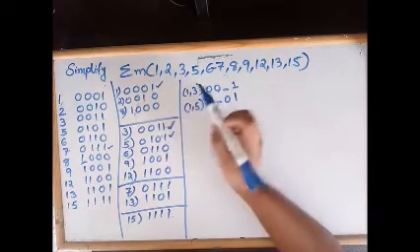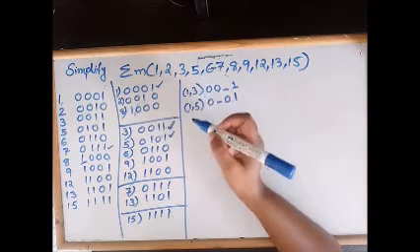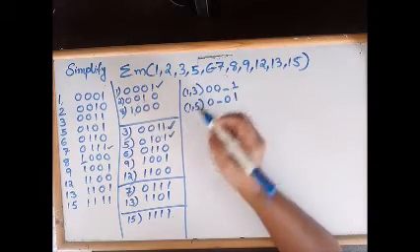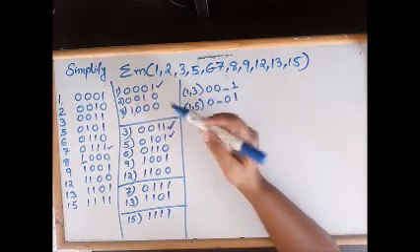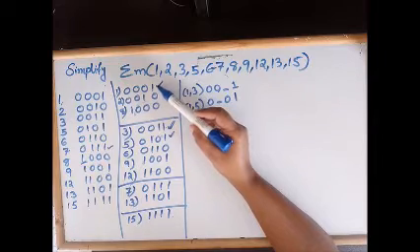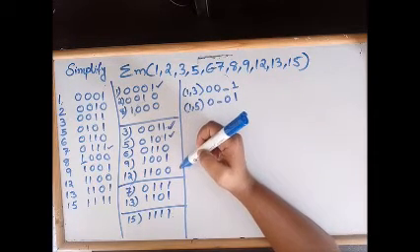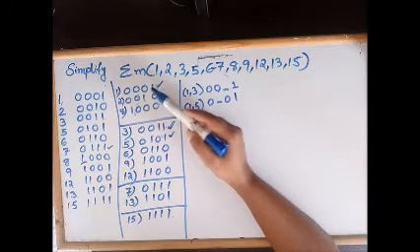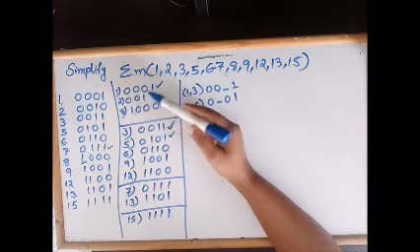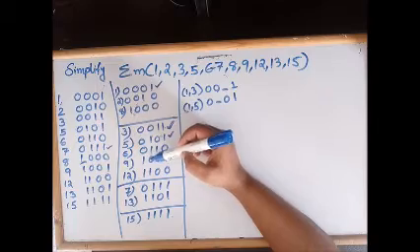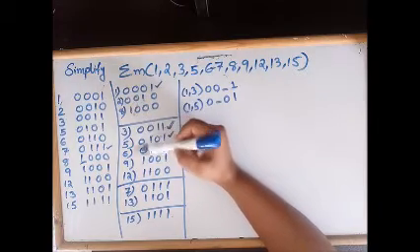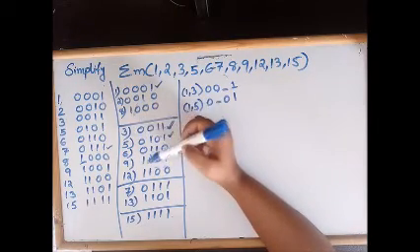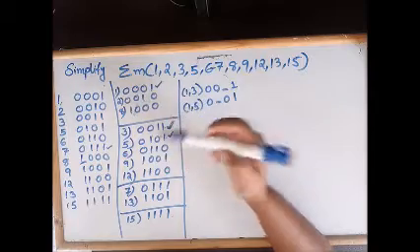So there exists more than one bit difference, so we cannot combine these two. Again consider the next combination, that is 1 and 9. When you consider 1 and 9, is it possible to combine? The LSB is the same, the next bit is the same, the next bit is the same, only the MSB changes. So only one bit change, so we can combine 1 and 9.